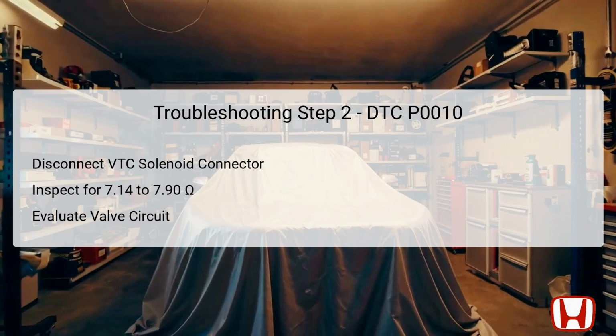This step is significant as it directly points to potential failures within the solenoid itself and validates whether further inspection of the external circuit is necessary. For this troubleshooting step, the technician should disconnect the PCM connector to further investigate potential circuit failures.